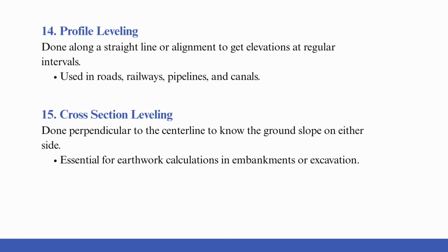Now the next type of leveling is cross-section leveling. It is done perpendicular to the center line to know the ground slope on either side. Cross-section leveling is essential for earthwork calculations in embankments or excavation.